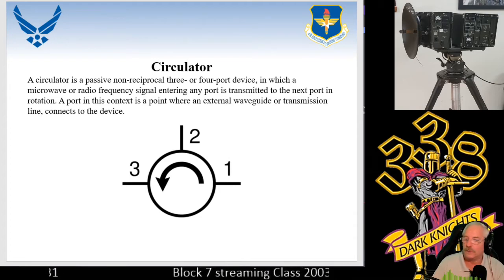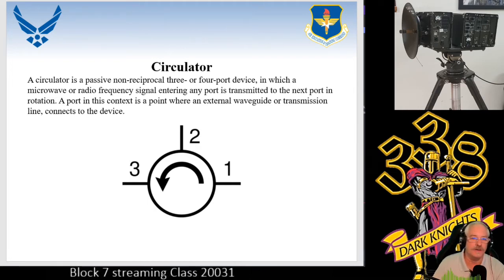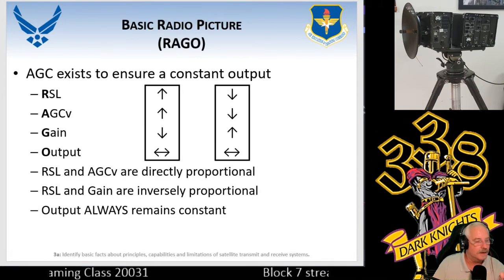In our case, we're going to have a 3-port system. Passive, non-reciprocal 3 or 4-port device in which a microwave or radio frequency signal entering the port is transmitted to the next port in rotation. In other words, it's able to decide which one is transmit and which one is receive. Crazy stuff in this equipment.